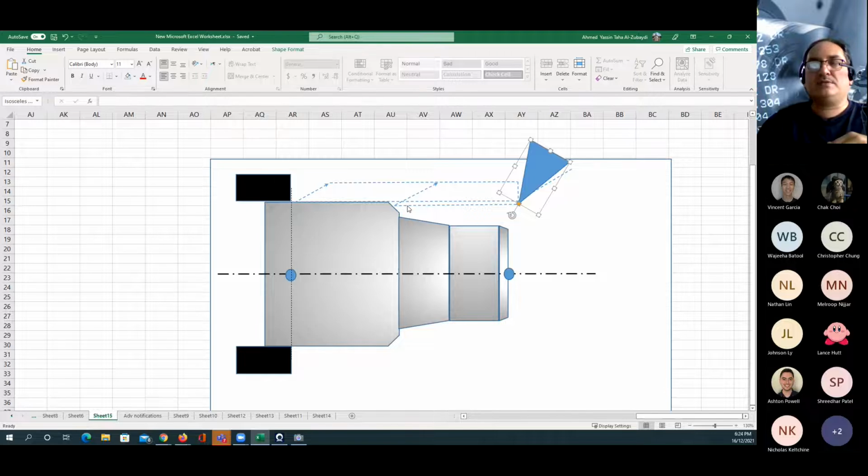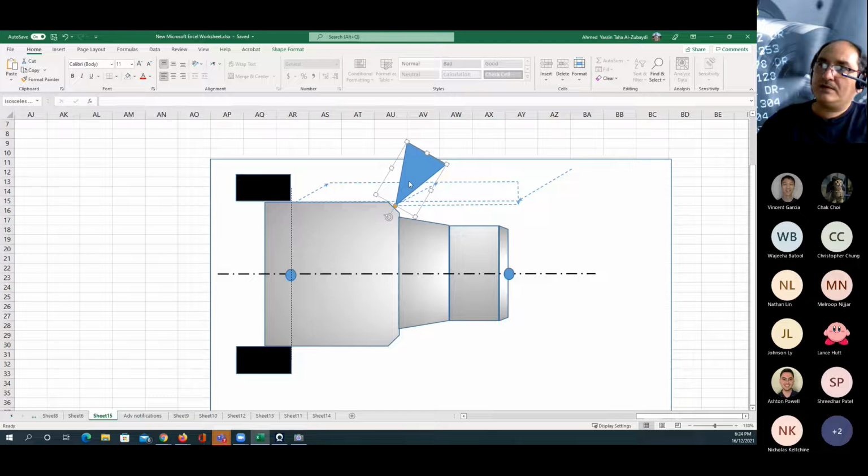68, that means it's 1 millimeter. So again, to take it further for another 1 millimeter, again, to make it as 66. So the depth of the cut here is 2 millimeters. 66, the cutting tool is here. Then again, to send it as G01 to that point here. So I removed a layer.